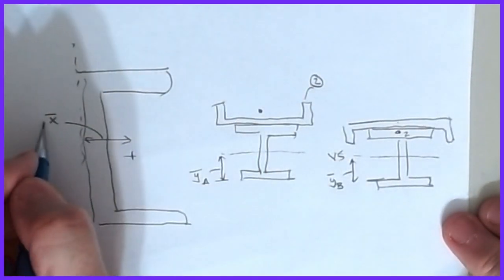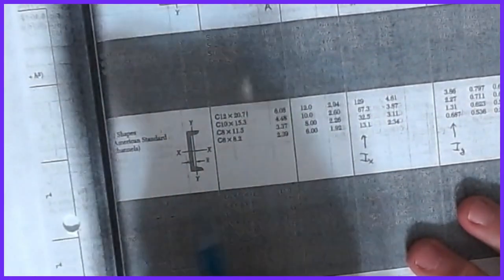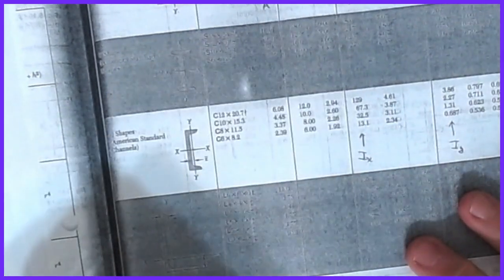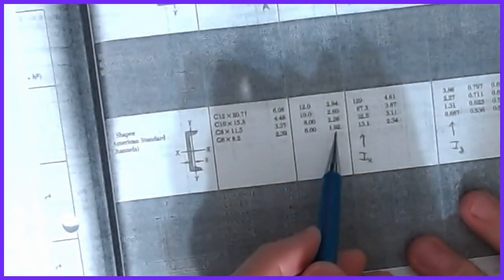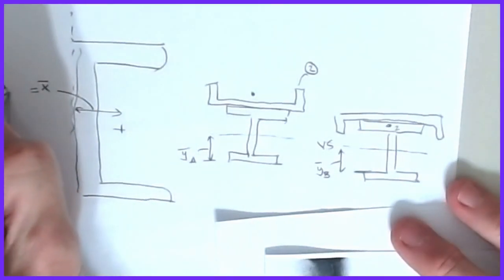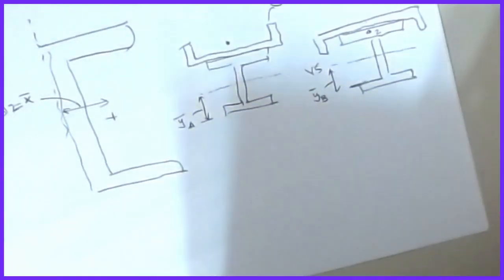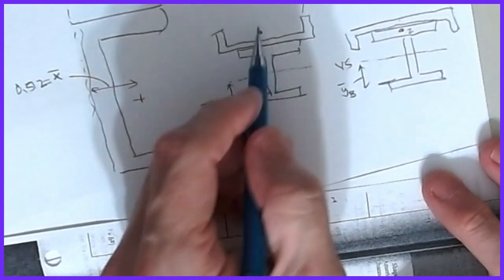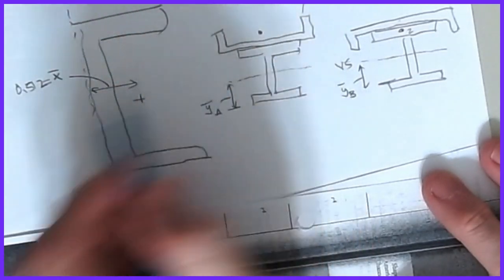So, in the table, in that particular case, they said x bar for this small guy would be depth, width. It's here somewhere. Okay. Well, wherever it is, I'm not seeing it now. Axis y. Oh, there it is. It's this value. This 0.812 or 0.512 inches. So this is 0.512 inches. All right. And so you can see that that makes a difference on that parallel distance. And so you've got to watch the orientations on this.